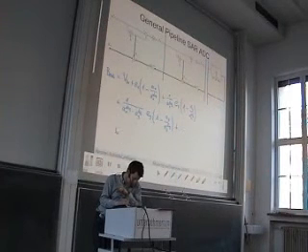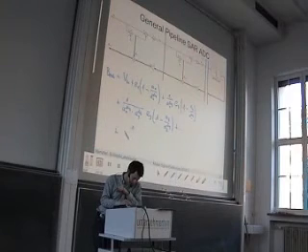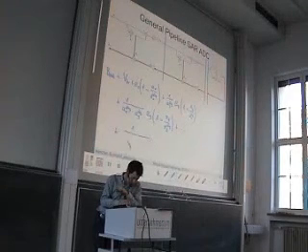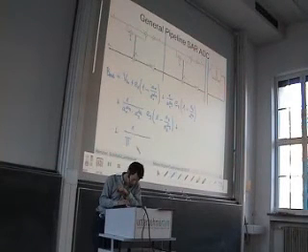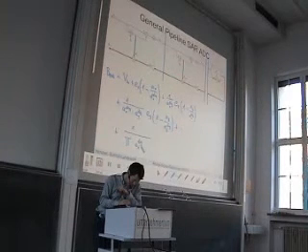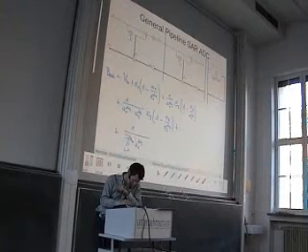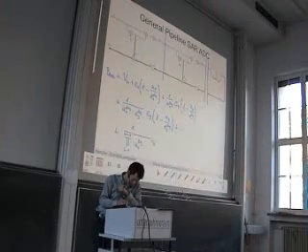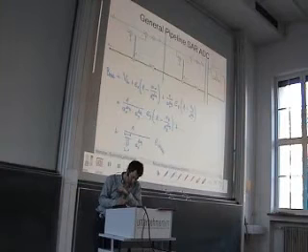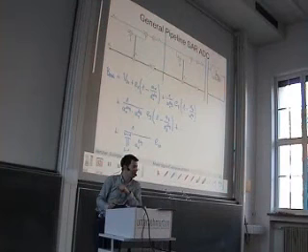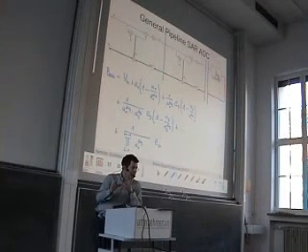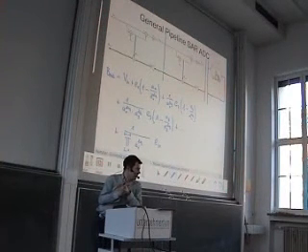And finally we have our last stage, and the last stage sees all the scaling factors on the reverse way. So we have a product of Ai digital, where i is equal to 1 and can go to n minus 1, times the quantization error En of the back-end ADC, which is this one. So, huge, terrible formula.